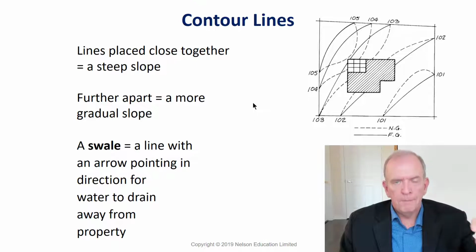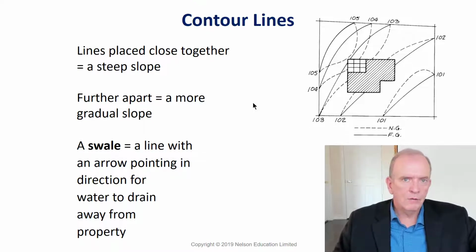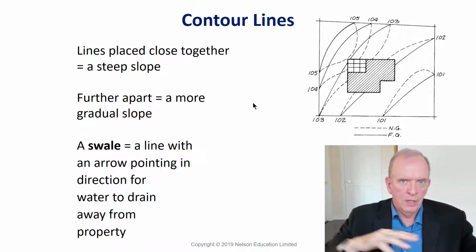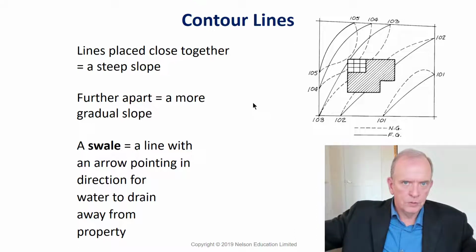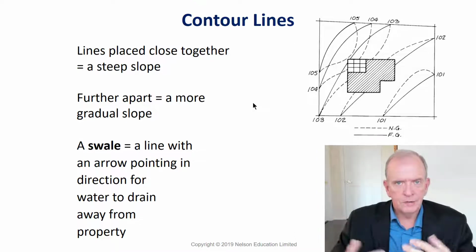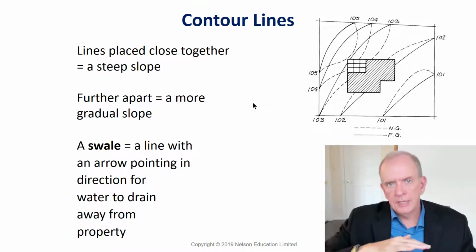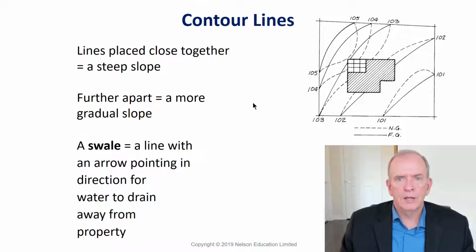If it's a benchmarked elevation, usually you find these little monuments on the side of buildings. It'll be a registered elevation, and then a surveyor adjusts the elevation from that point. Wherever that point is and it's at 100, if you've gone up 3 meters, that just means the grade is up 3 meters. And an OLS, an Ontario Land Surveyor, can mark out the grading for the whole property and ensure that it gets graded to those elevations.